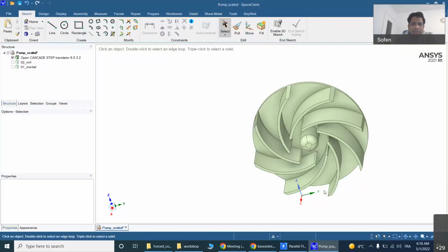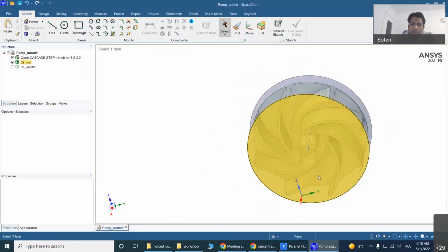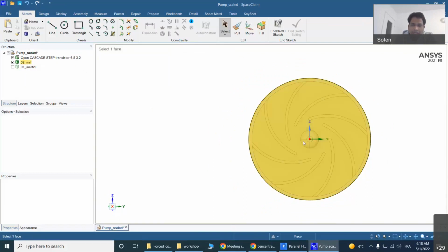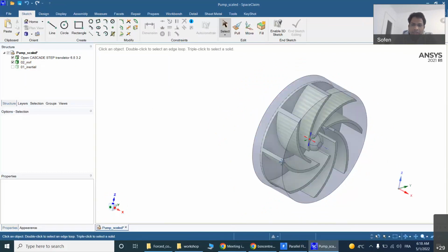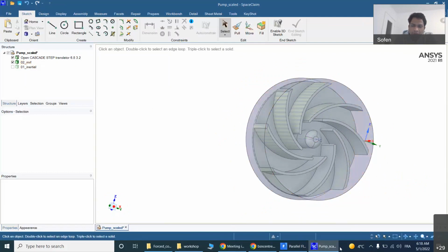this is something that is rotating. So normally we have prepared a cylindrical zone across it. Normally it should be rotationally symmetric along an axis. We have created a cylindrical zone out of it. We do not want the solid to be taken into the solver, because we are not solving any conjugate heat transfer problem.